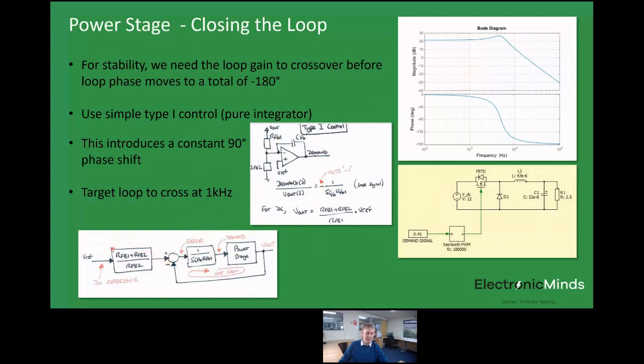There's also a term here on the front end, which is just a DC term, because we have the reference voltage here, which I think in my application example I've used as 1 volt. The actual output voltage, the set point, is then going to be governed by the potential divider of RFB1 and RFB2. So we have to include a block here to give us that correct reference point. So this is just a mapping of this circuit into a closed loop representation.